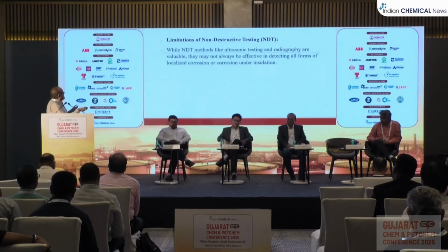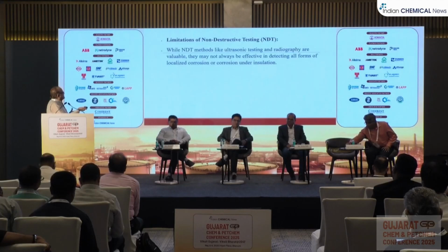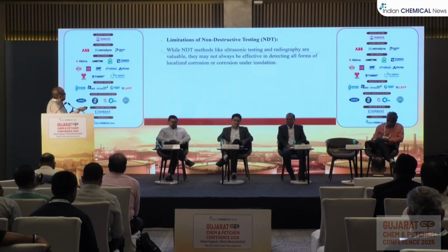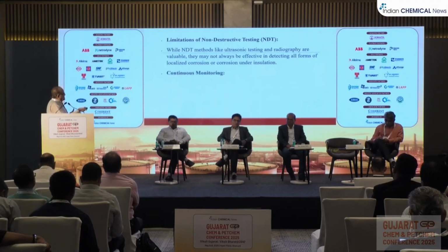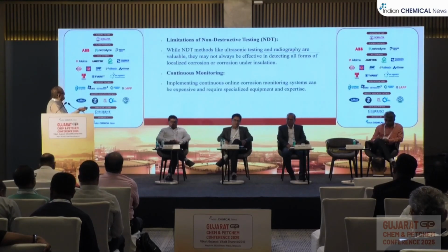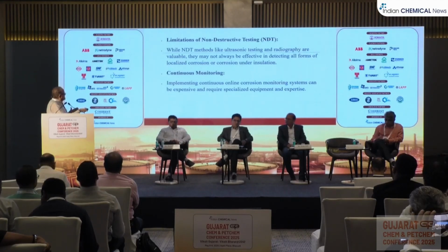Limitations of non-destructive testing. While NDT methods like ultrasonic testing and radiography are valuable, they may not always be effective in detecting all forms of localized corrosion or corrosion under insulation. Continuous monitoring, that is very important, sir. Implementing continuous online corrosion monitoring system can be expensive and require specialized equipment and expertise. Operational and maintenance challenges.